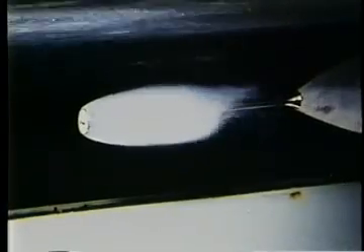With high-speed photography, we can see more of the details of this complex flow. The flow at the end of the cavity re-enters and moves upstream. This re-entrant flow is illustrated more clearly in the cavity trailing our supercavitating hydrofoil. Re-entrant flow is characteristic of such cavity flows. The momentum flux in the re-entrant jet is equal to the pressure drag of the body. The jet kinetic energy is dissipated.